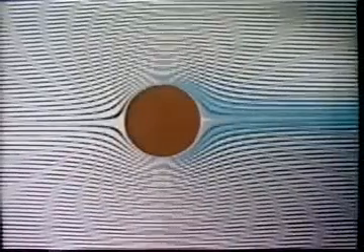When they are deflected by a thin disc placed between the sheets, they assume the same form as those of an ideal fluid when deflected by a cylinder of the same cross-section. Now, instead of a solid body, a source is started in the flow. Here is the flow round a half body. The red dye shows the internal streamlines.